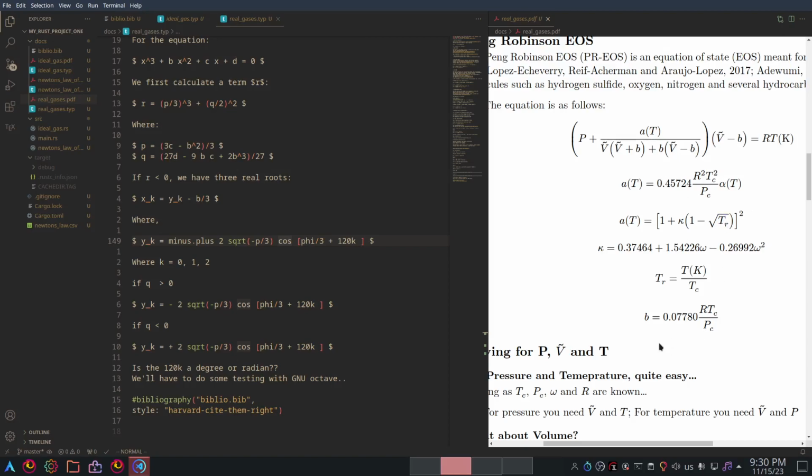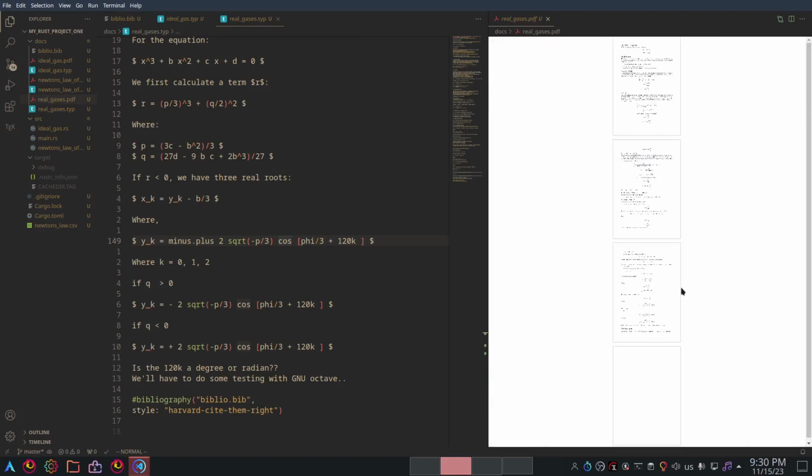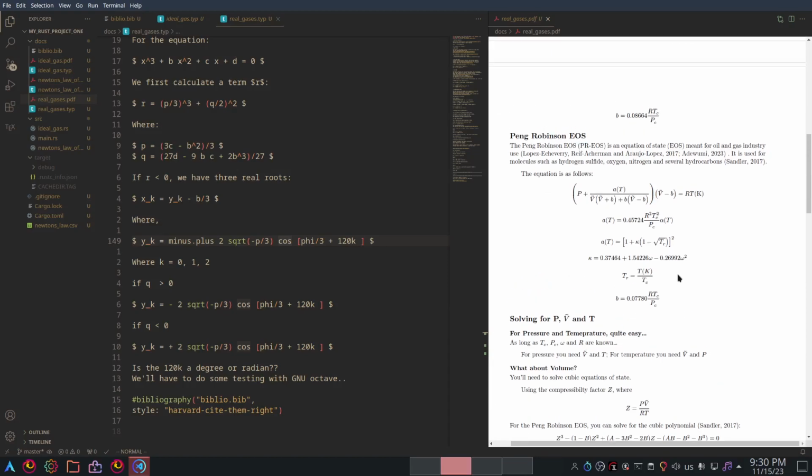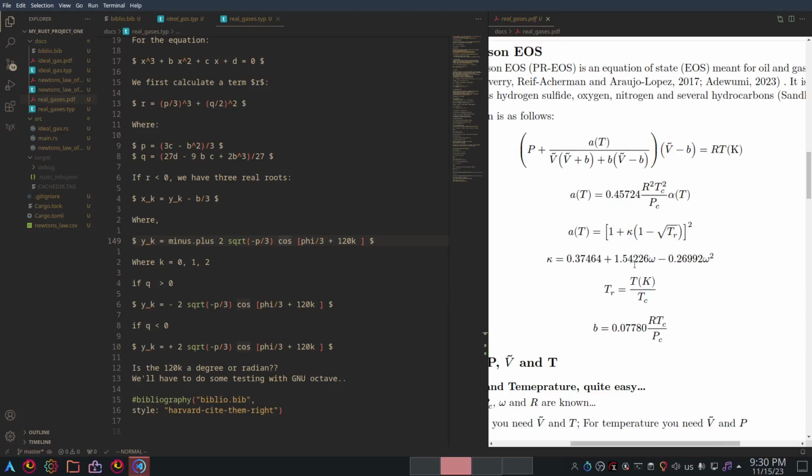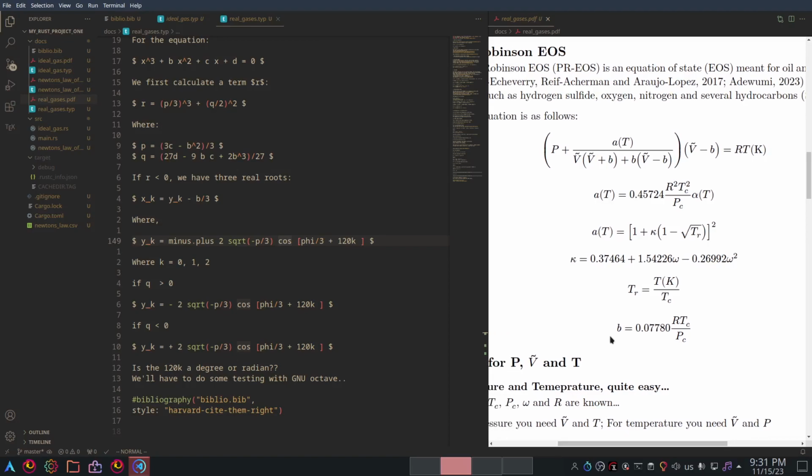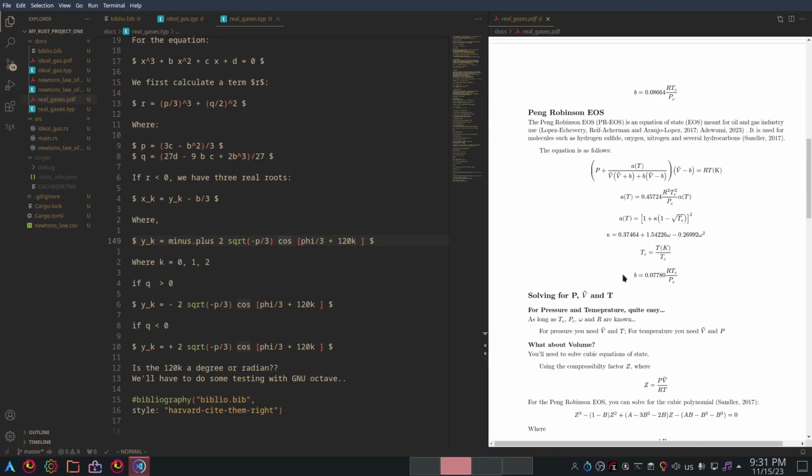The most challenging one is the cubic equation of state. Of course, nowadays you have lots of numerical solvers, where you can solve it using Newton-Raphson method or some other kind of method to find all these three roots. Unfortunately, those methods are a little bit slower computationally. So there are thankfully analytical solutions, but they're pretty involved in themselves.